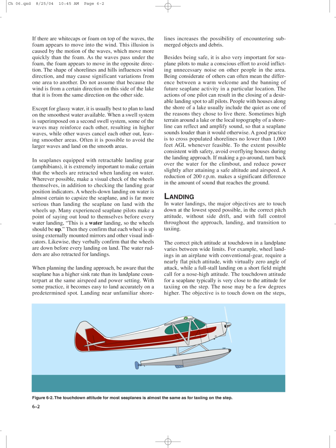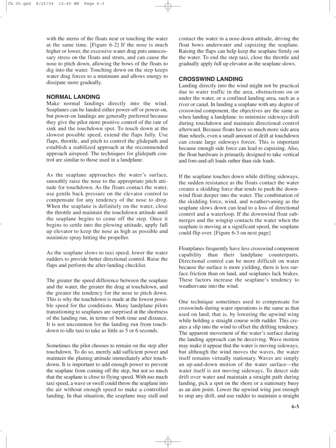The objective is to touch down on the step, with the sterns of the floats near or touching the water at the same time. Figure 6.2. If the nose is much higher or lower, the excessive water drag puts unnecessary stress on the floats and struts, and can cause the nose to pitch down, allowing the bows of the floats to dig into the water. Touching down on the step keeps water drag forces to a minimum and allows energy to dissipate more gradually.